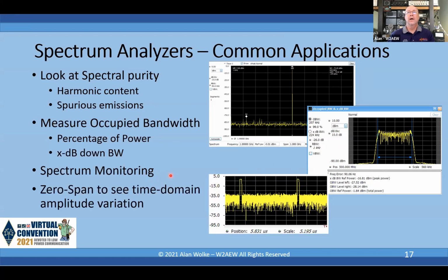Okay. And many spectrum analyzers give you the option to do what we call zero span, where if the span is set to 0, that means that you're setting a center frequency and not sweeping off that center frequency. So now you've turned it into an AM radio. And with that AM radio, you can plot out amplitude versus time to look at pulse signals, maybe CW pulses or something like that. But that's what zero span operation is.